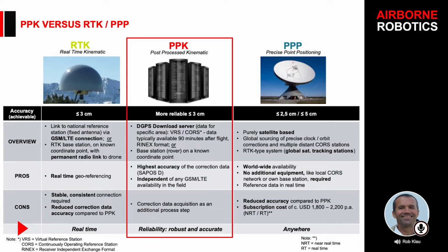The processing algorithm is a lot more robust, and where we find often customers will be traditionally using PPK post-processing and things come unstuck, they're not getting the accuracy they need, then this new hybrid PPP, PPK processing is more robust, more accurate, and you don't need to think about base stations. Where's your base data coming from and all that?